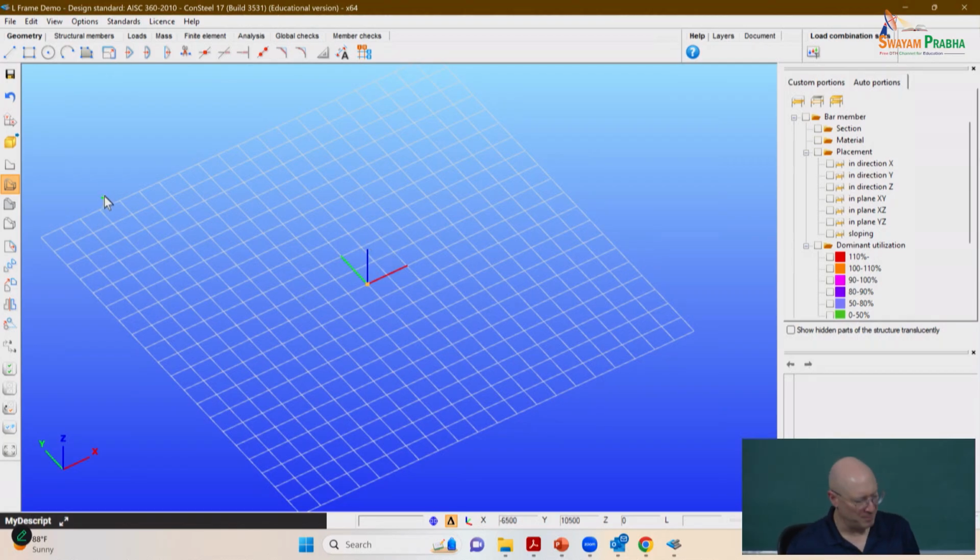All right, now the first major step, if we're defining a frame, is to select our structural member cross sections. You can see there's the broad menu at the very top, and then menu bars. Right now, the third level of menus is for geometry.